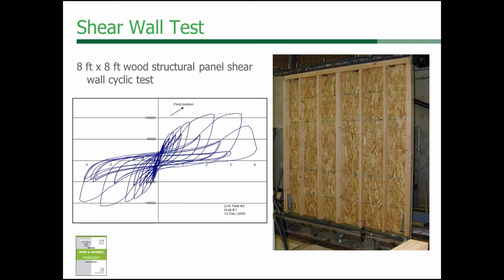Anyway, so now seriously, getting back into the shear wall and all what we're trying to accomplish here, and learning about stiffness and strength and what that all means to a shear wall. Here are some test results from an 8x8 wood structural panel that was tested using the CUREE protocol and cyclic testing.